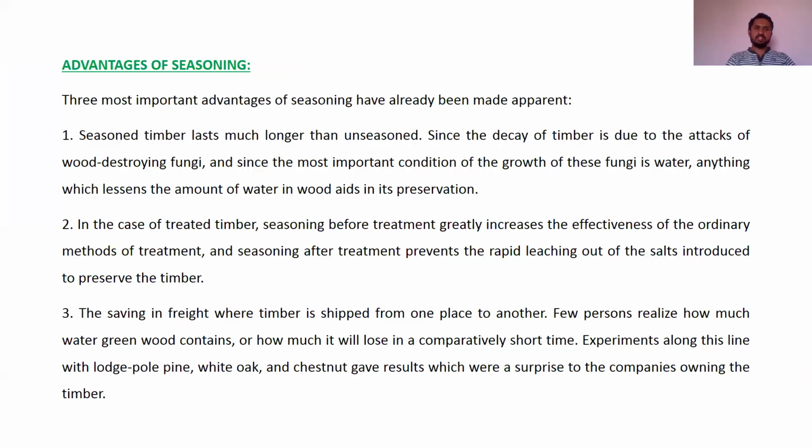Now coming to the advantages of seasoning. The three most important advantages of seasoning have already been made apparent. Seasoned timber lasts much longer than unseasoned, since the decay of timber is due to the attack of wood-destroying fungi. And since the most important condition for the growth of these fungi is water, anything which lessens the amount of water in the wood aids in preservation.